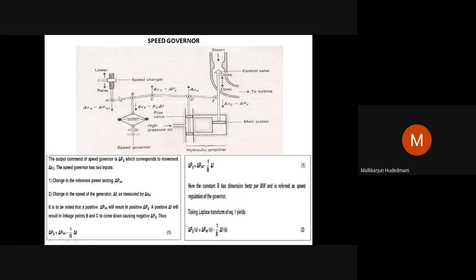It means to say the set point is shifted by this feedback network mechanically from the actual speed of the turbine, according to the shift obtained on the P reference proportional to the speed it is exactly possessing, and will have a displacement in position. Those displacements will permit the hydraulic oil to enter inside the chamber and make the subsequent corrections to close the valve or open the valve as per your requirement.